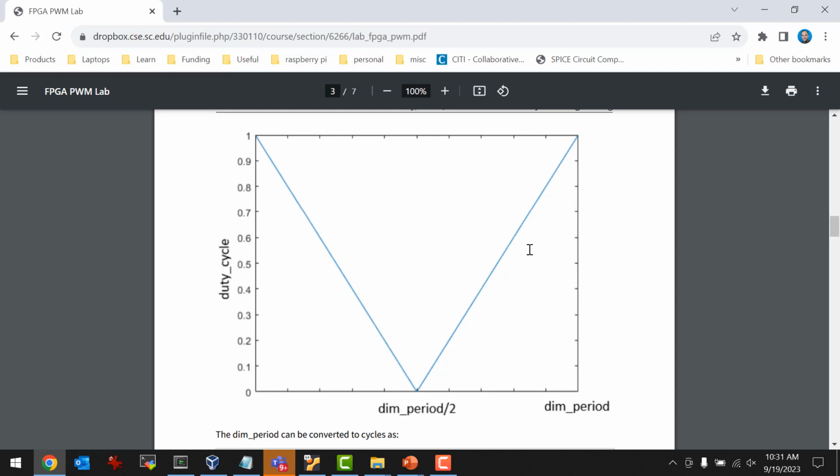The PWM constantly repeats, but over time, the duty cycle of that constantly repeating signal is being adjusted in order to implement the other thing that you're controlling on the larger time scale, right? That's what confuses everyone in this lab. That's the tricky part.